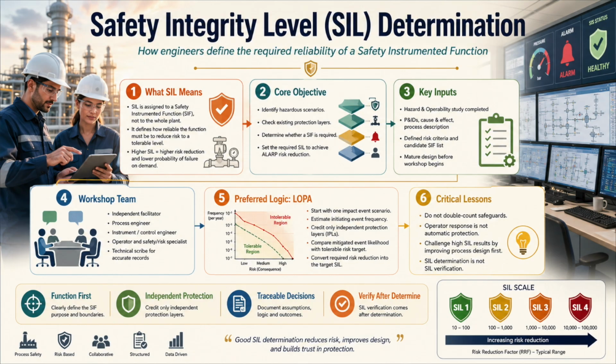The objective is not zero risk. Zero risk is not a credible engineering target. The objective is to reduce risk to a tolerable level and then continue reducing it where further reduction is reasonably practicable. For low demand functions, the key measure is average probability of failure on demand.